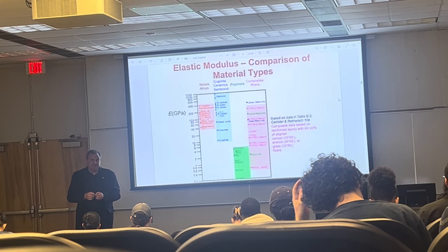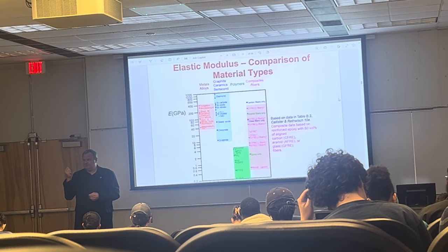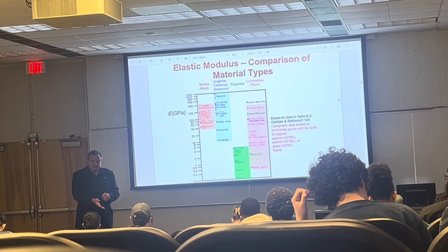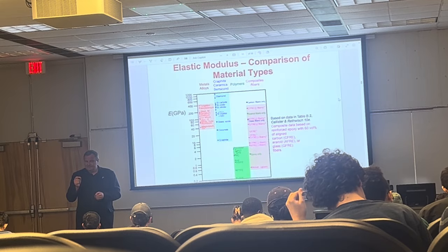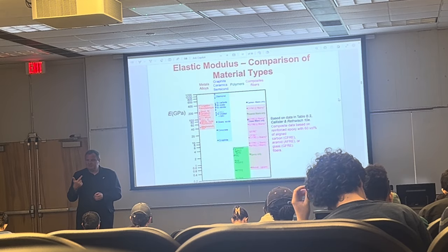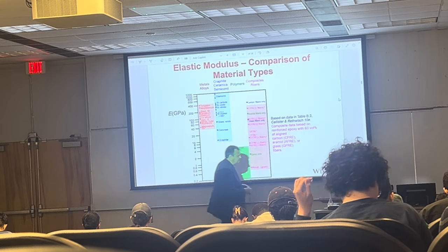That's the reason when you go on the beach, you have your glasses, whether they're made of plastic or whether they're made of glass, don't put them in the sand, because the sand is going to scratch your glasses because of small contact area. And hardness and the scratching business, they're all measures of plastic deformation, not elastic deformation.